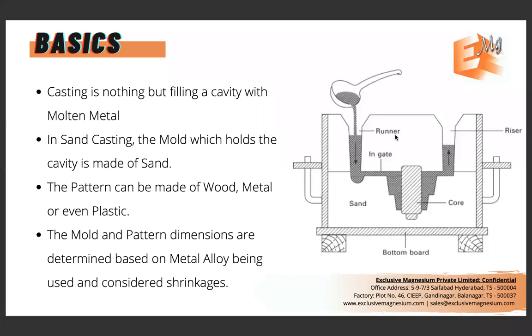That's majorly it. Create this cavity. Every sand casting will have a runner, through which the metal is poured. It fills up the cavity, and the riser indicates whether the cavity has been completely filled or not. So that's the basic logic. The pattern to create this cavity, which is packed within the sand, can be made from wood and metal, but there are other companies which use different forms of engineered plastics and polymers for further very complex designs. 3D printed molds, as well as patterns, have been coming up too.